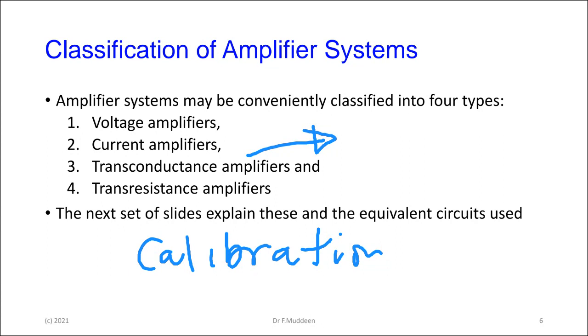The only way you know is to calibrate it, which means that you put something known, in the case of multimeters, known voltages and known currents, into the device, and you compare the reading against a known value. The values are, of course, standard voltages and currents.